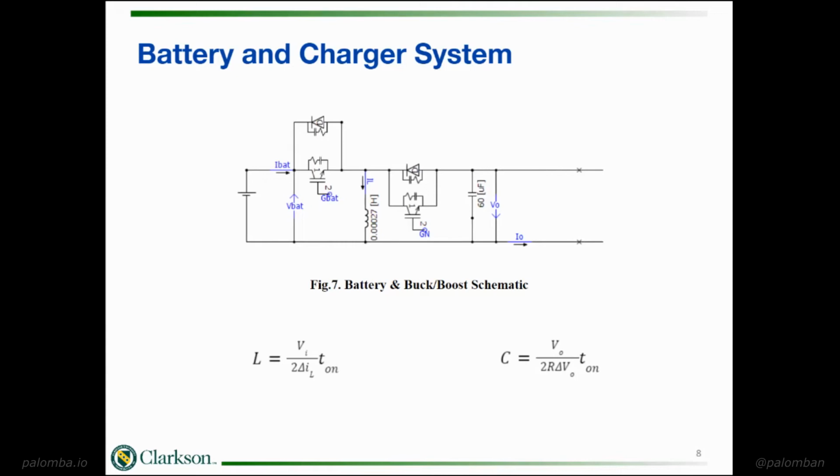And we also included an aging factor for the battery of 1.25. So assuming that over time the battery reduces to 80% of its original capacity, and a 1.1 design margin factor for additional conservatism. We designed our pack for a total of 825 kilowatt hours.